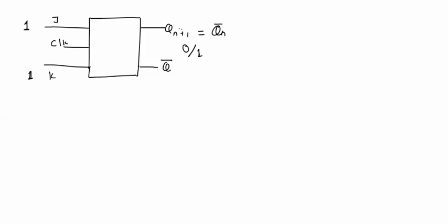See how this clock signal is applied to the flip-flop in order to trigger it. Triggering means the instant where the flip-flop will be triggered, it will look at the inputs and accordingly the output will be changed. If clock is not applied, the flip-flop is not triggered. If the flip-flop is not triggered, even if we have applied any input, output will remain in the previous state. Output will not change according to input.